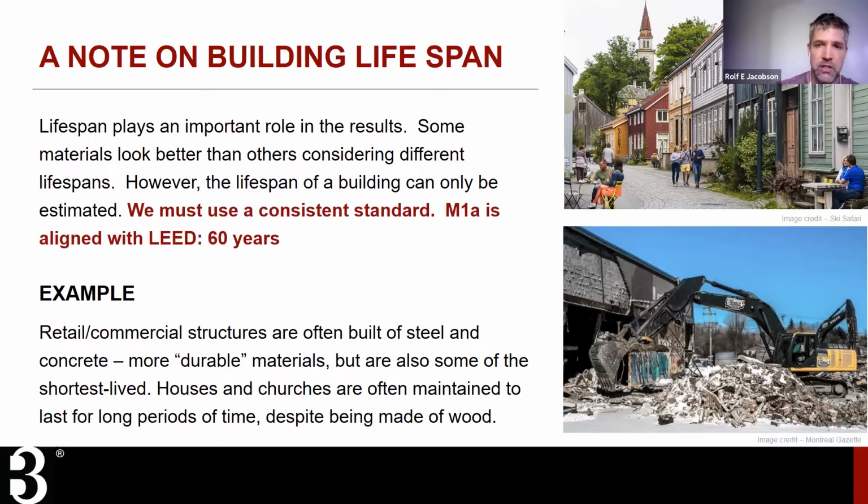So we have to have a consistent standard. For the B3 program, we have aligned ourselves with LEED, and LEED selected early on 60 years as kind of a consistent lifespan for the building when we're doing LCA analysis. So that's what we use in all the LCA models that you will be producing. Just set that building lifespan at 60 years, no matter what building, the construction materials or building types that we're modeling.